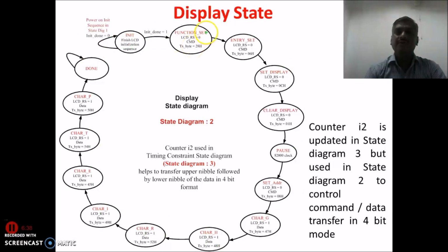Now here for the function set, we are sending the command. Now we are working on the command because data sending starts from this point onwards. These are the steps I am using for sending the commands. Here the RS register select must be 0, and the write and read terminal WR should be again 0 because we are writing. We are sending the command.